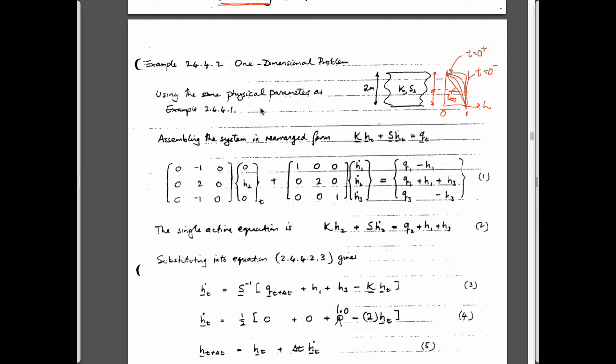You'll remember that the conductance matrices were 1, -1, -1, 1. You may or may not remember that the storage matrix was equal to 1, 1, in its lumped form. The matrices you get by putting the conductance matrix here for element 1, the conductance matrix here for element 2, likewise for the storage terms. The term here is just the sum of the two that happen to coexist at that particular location.